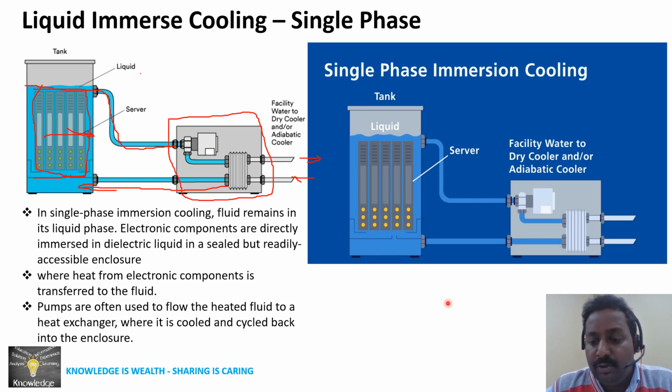It is the most effective method. This is the maximum level to which we can optimize energy, where the medium is engineered fluid, not air. It is straight away extracting the heat generated by the rack itself, so there are no losses in it. So there is maximum energy saving in this concept. The only part we need to mitigate is operating challenges, like the condition of the heat exchanger, coil condition, and water quality. Those parts we need to take care of for smooth operation.